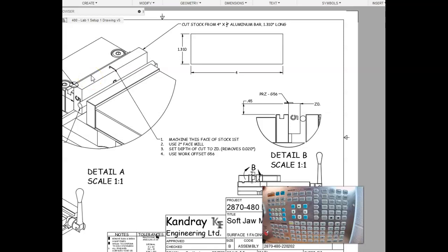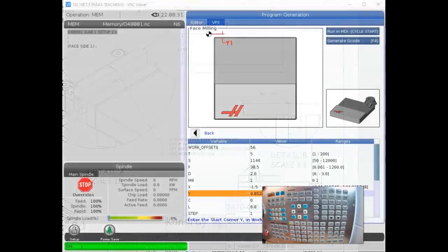So our shift is going to be half the diameter is 1. We would want probably a 45% offset on the diameter, which would be 0.9, which would mean we would shift the center of the cutter 0.1 in the Y direction, and that's what we'll do. So we come here and we enter 0.1 for that.